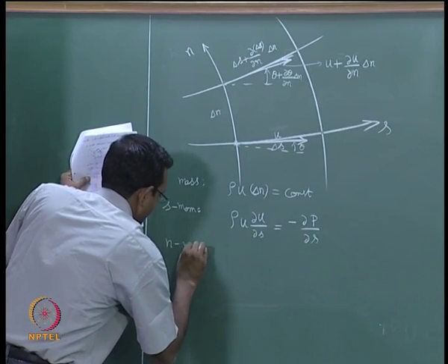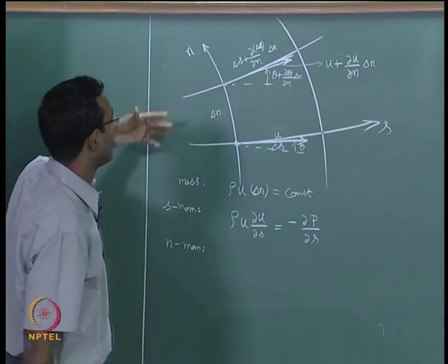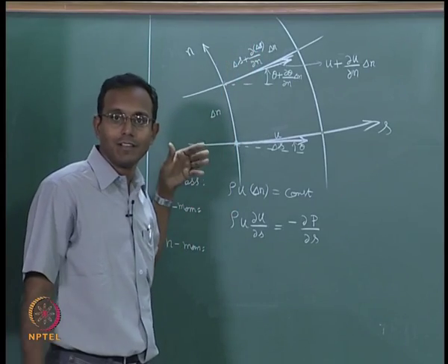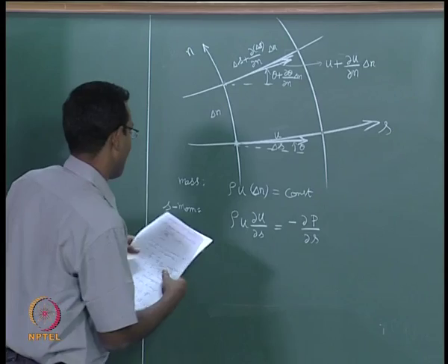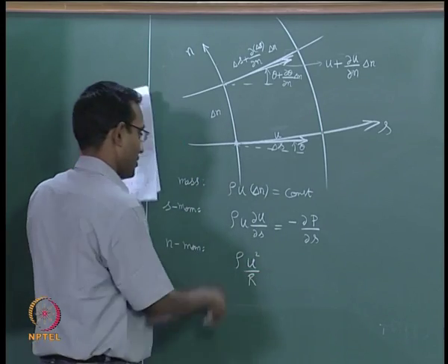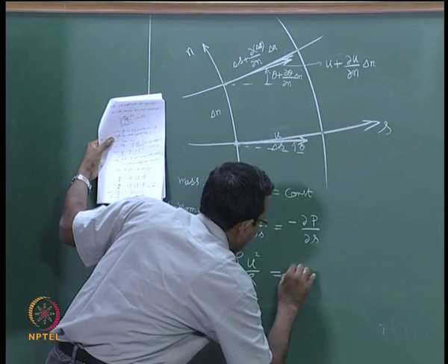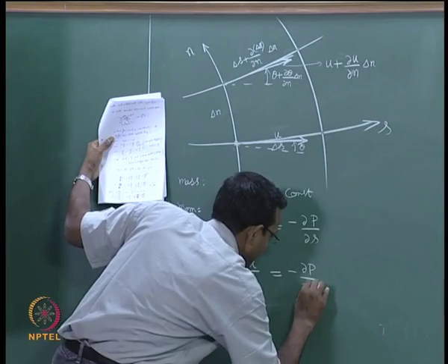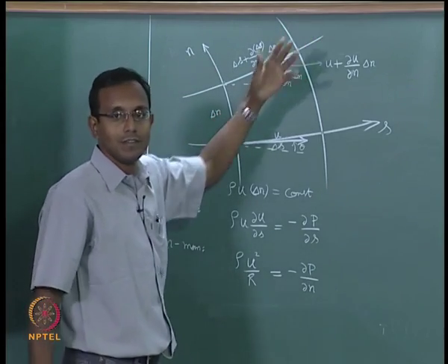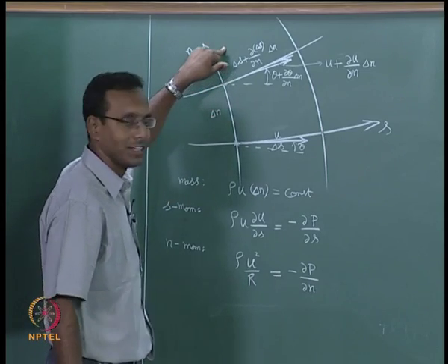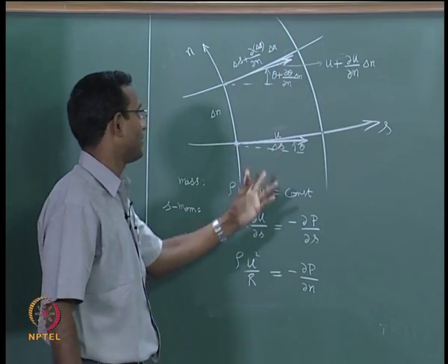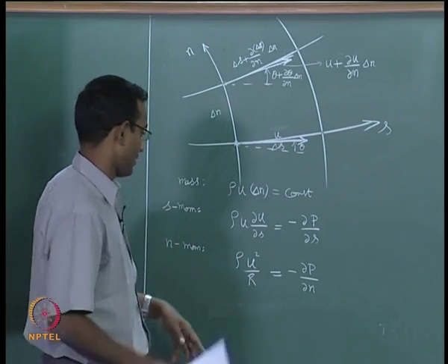Next one is the normal momentum equation, where now I have to think about the streamline being curved and curving. If it is curving, then there is a force perpendicular to the velocity vector, that is when a streamline will turn, it is like a centrifugal force or centripetal force. Okay. So I will write an expression for that, that will be rho u squared by r, this is your centripetal component. This should be given by minus of ∂p/∂n. The normal force, if my pressure here is higher than pressure here, then my streamline will curve up. As the pressure goes from lower n to higher n, pressure decreases, which means my streamline will turn up. That is what this is showing here. Okay, minus of ∂p/∂n is the net force upward, that is going to cause a centripetal acceleration. Okay, that is this term sitting here.